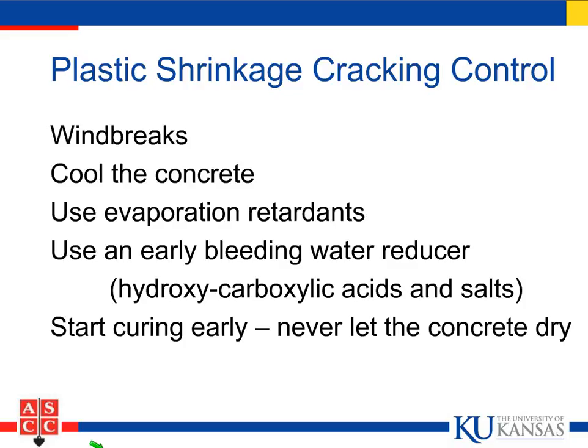You can use evaporation retardants. Use an early bleeding water reducer, and you can start curing early. That is, never let the concrete dry out. So if you have a job where you can actually have burlap on it, and you don't care about the surface, you don't have to get in there and trowel it, then this works very well.